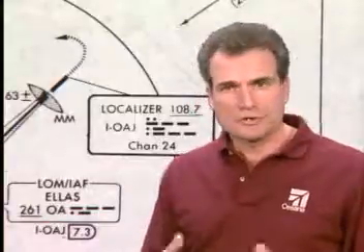You see, the transmitter for the DME installation is somewhere near the localizer antenna off the far end of the runway. And that's not the same place as the airport reference point that the GPS database uses for the airport location. In fact, at a big airport, the difference between them could be a mile or more.